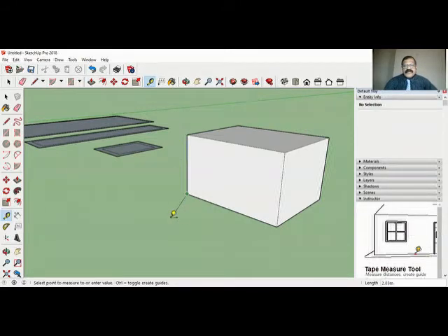It also can be used to draw guidelines. What are the guidelines? I want to draw a door from here, 2 meter height. I don't know where the 2 meter is, it's a little confusing. So what I will do is I can use this. Click here. You see it's drawing a parallel line.